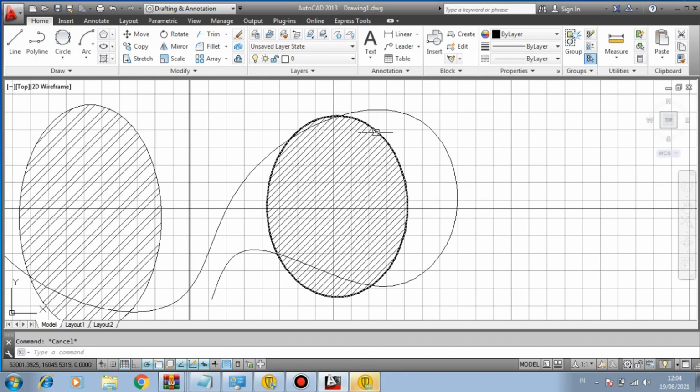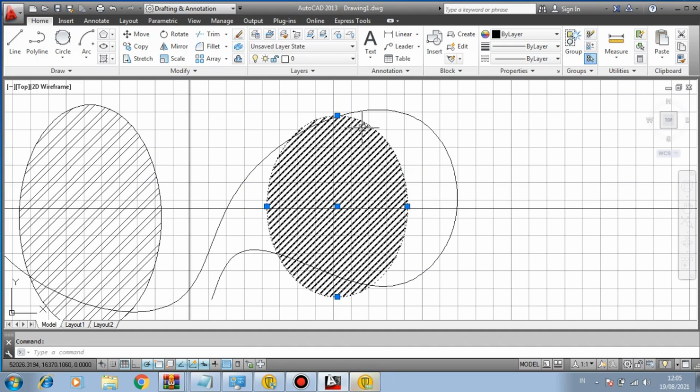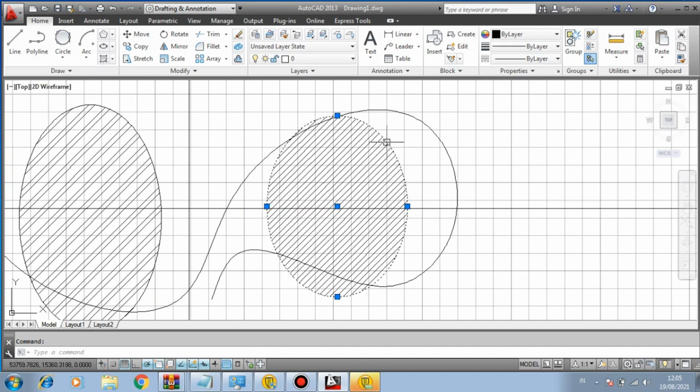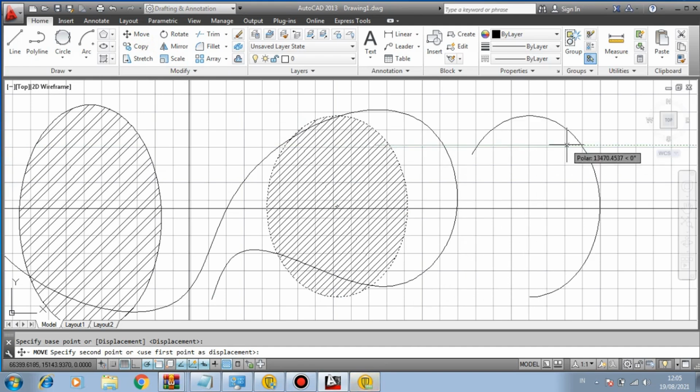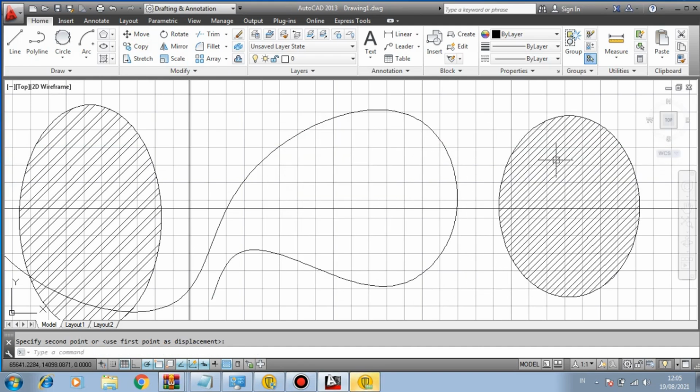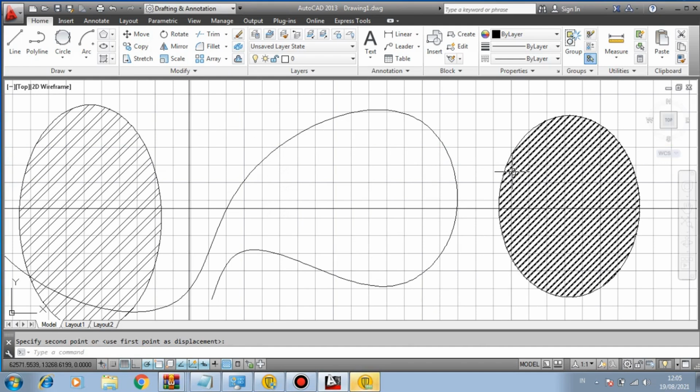For example, I want to precisely move this particular ellipse object. If I carefully click on the line, only the outer outline will actually move, which is not what I intend. The arc doesn't move along. Click the object, click move, then click the object again. So move the mouse to the right and then click, and it will move.